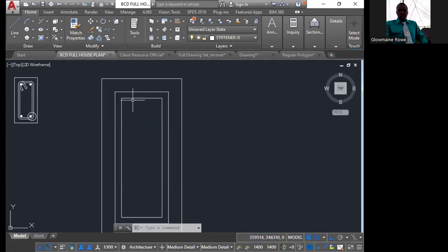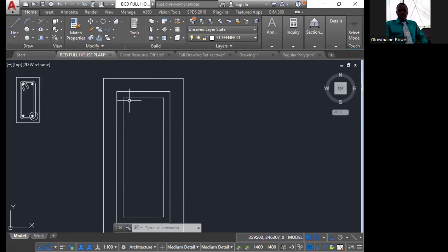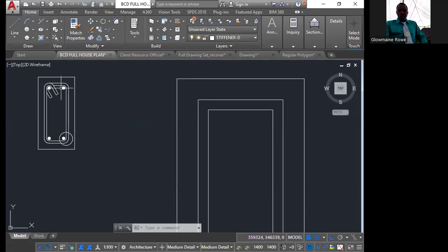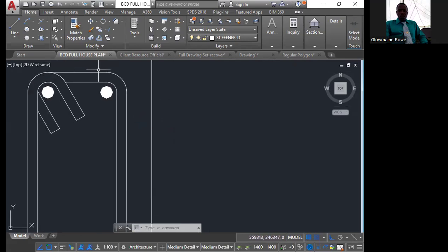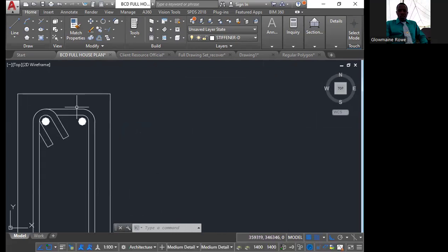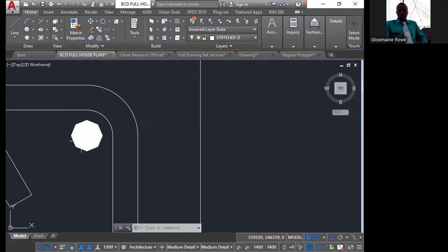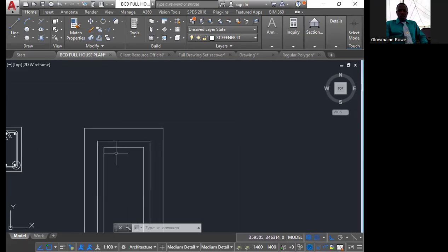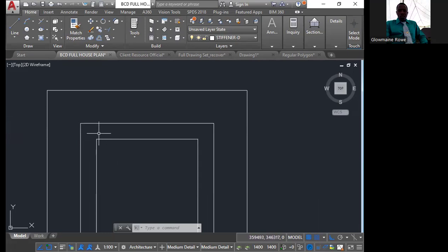So we're gonna use a nice little command, one of my favorite commands, to get the corners of your steel tie to be rounded and not angular. So this 1/2 inch steel bar here, the diameter is 12 millimeters. So you want the radius for this to be 12.